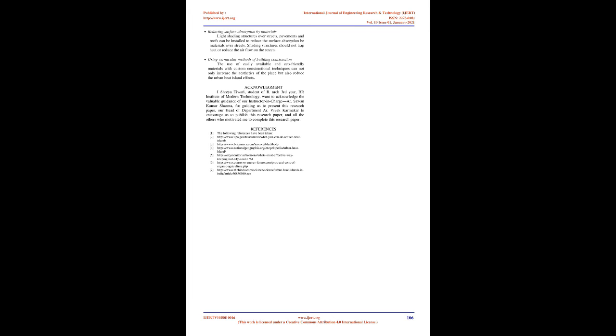Improving urban geometry to reduce urban canyon effect caused by them. The urban geometry should be improved by widening the streets to provide circulation and should be supported with vegetation so that the air is not blocked by the surrounding houses in the narrow streets.